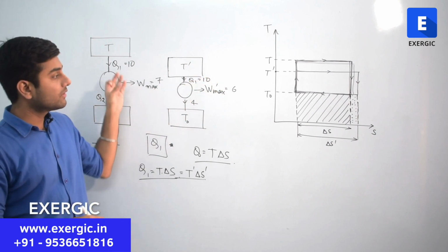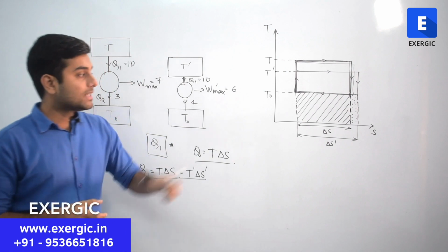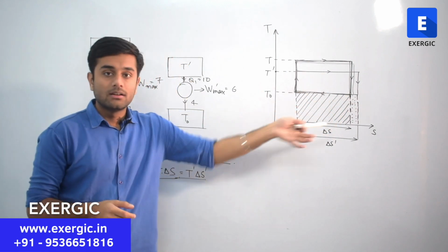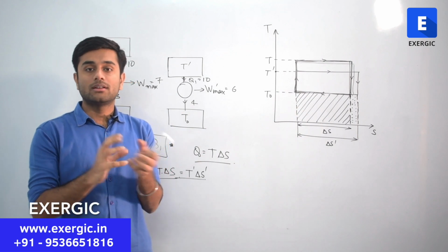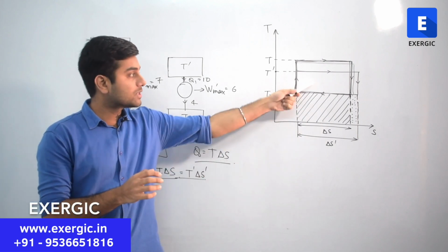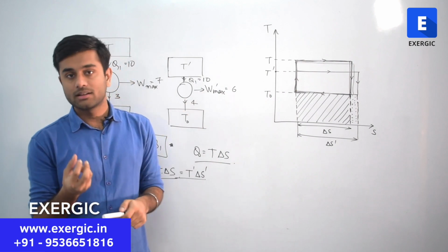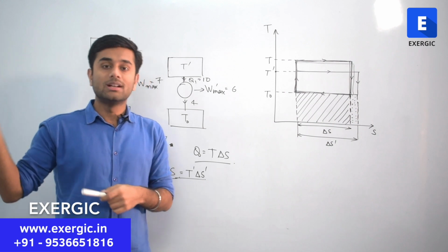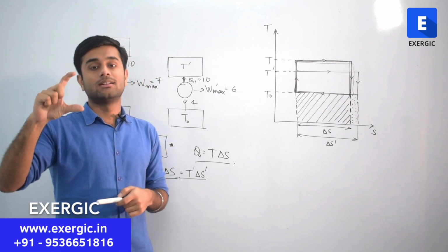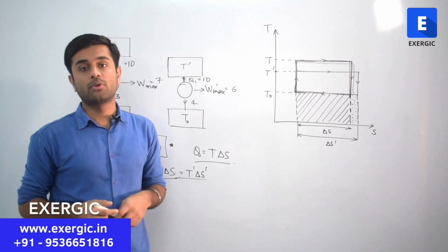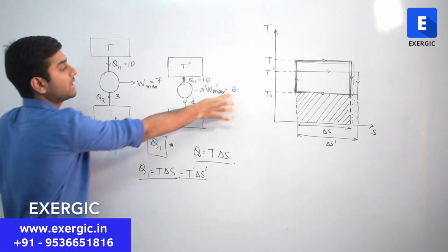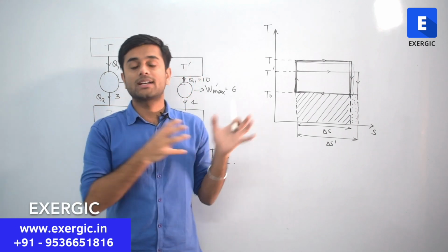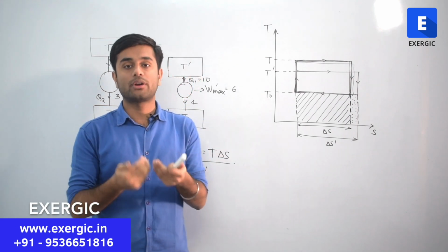So this is something which we already know of, correct? By seeing that unavailable energy increased, we concluded that the work, the available energy, must decrease, correct? Because Q is same. But that we have already concluded from the theory, that the temperature range decides how much work is to be produced. If the temperature range decreases, work decreases. We had already concluded that earlier, correct? So the graph is also supplementing what we already know.